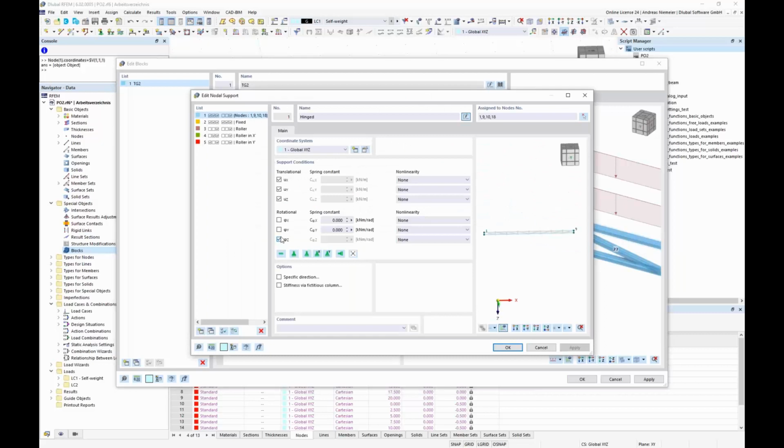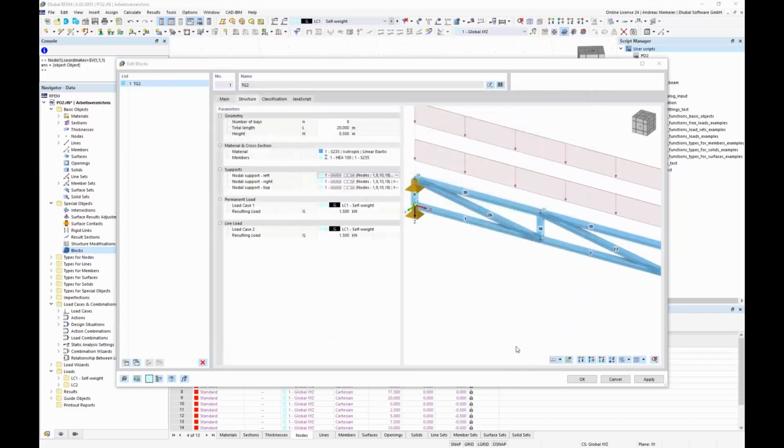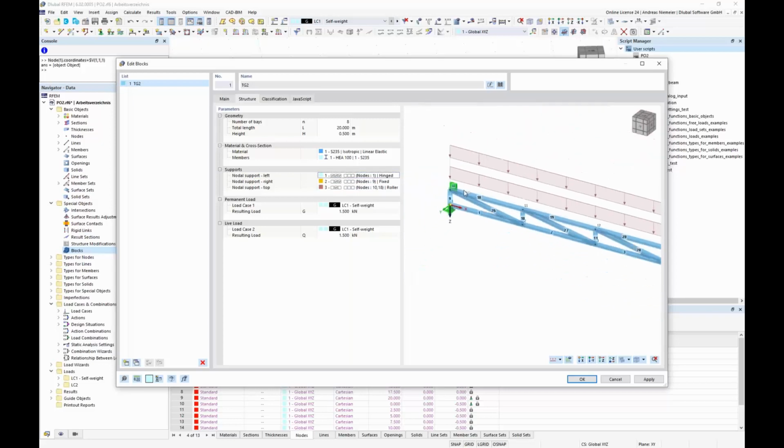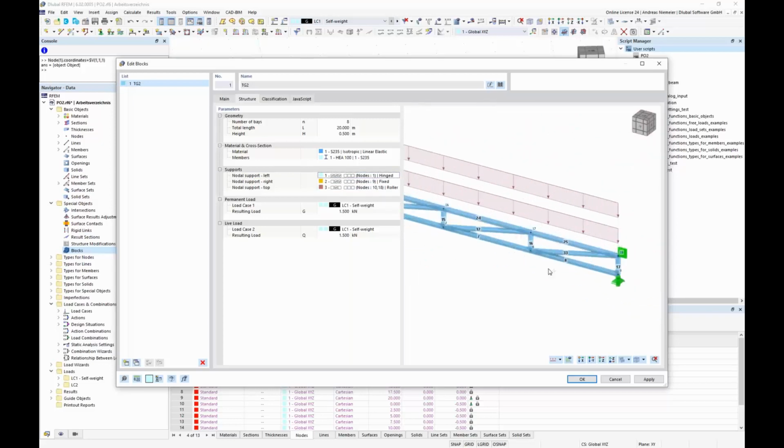Here on the corner we use, let's say, a rigid support in all degrees of freedom, the other is maybe without constraint in x3, and the last supports so that it does not fall out of the plane. So we have here node 1, node 2 and 3. And we have here also a clear support, and for the loading I defined it so that we get the sum